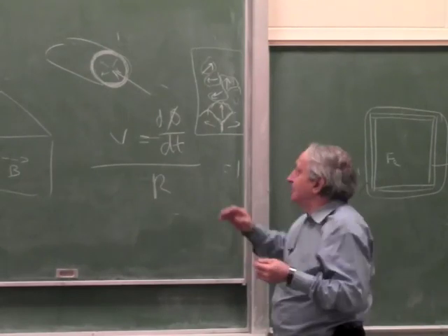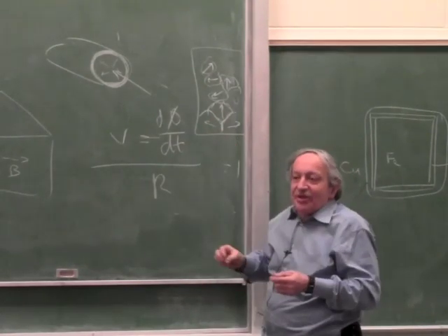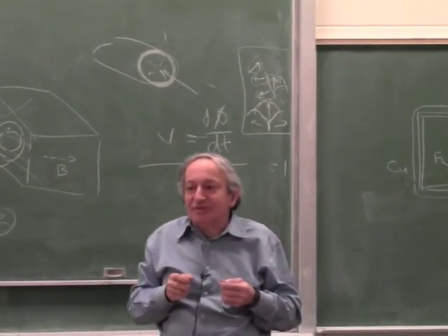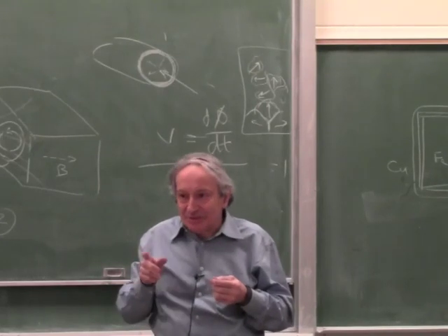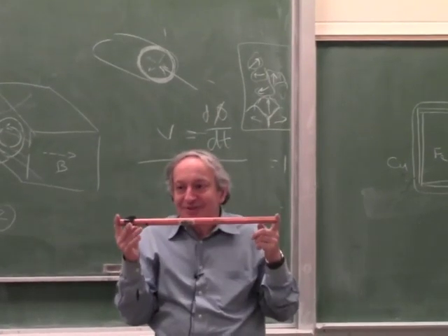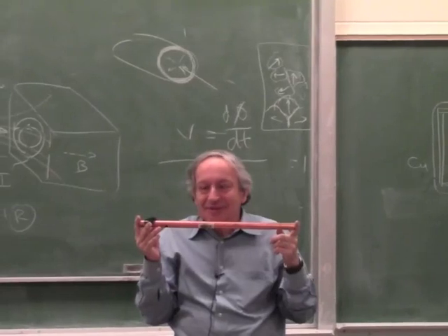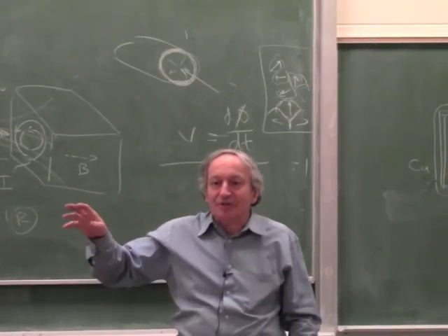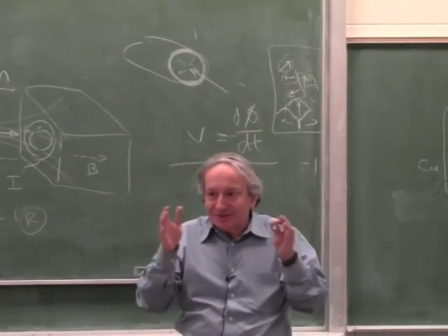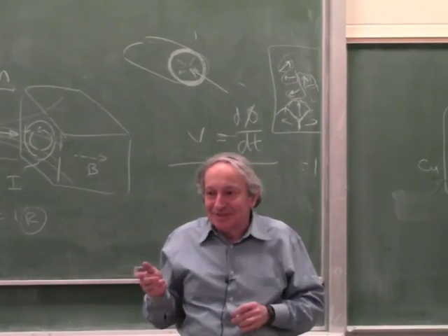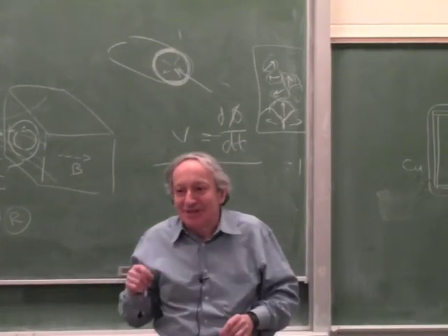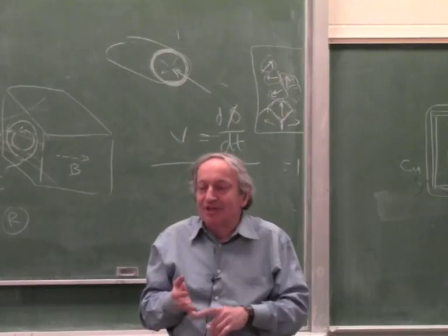Now as you magnetize it, these boundaries start shifting, so there is some mechanical movement as well. This is easy to prove by the fact that there is such a thing called magnetostriction. Do you know what magnetostriction is? If this is a piece of steel and I magnetize it, the length changes, so something mechanically has to move inside too. When you walk near a power transformer, you can hear it humming. This is magnetostriction. The whole transformer is growing and shrinking 120 times a second. Anyway, all this is getting too detailed for the time we have, so read up about magnetic domains and magnetostriction.